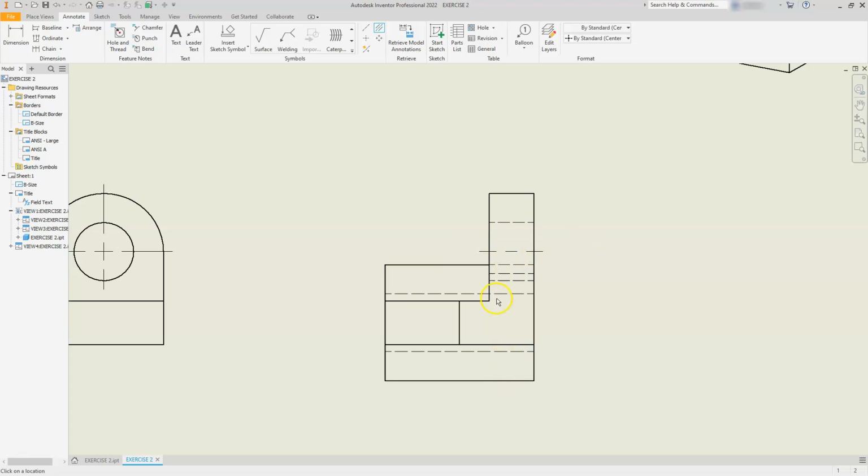With this one, I'll show you the other option of creating that with the center line command. So let's select the center line. I can select this midpoint, and then I can come over this direction and select this line. You can see that it went crooked because I did not select the midpoint. In this case, it might be easier to select the bisecting one. Okay, so I'll show you that one in another video later.